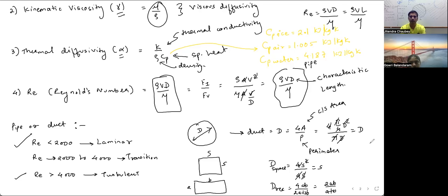Okay, these are all the numbers. First of all, you need to calculate. Once you know the numbers, then the most important step would be to calculate the Nusselt number. Then after the Nusselt number, mostly it goes with the calculation of the coefficient of convection H. And then with the coefficient of convection H, you can calculate Q. Q equal to H delta T.